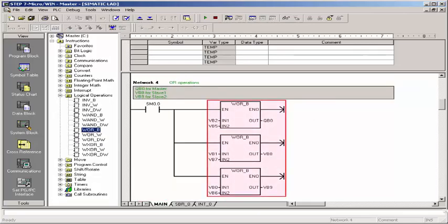The byte-by-byte logic OR connections of rising and falling running lights per PLC occur in network 4. For the master, the result is directly output to QB0, and for the slaves it is intermediately stored in V memory byte 8 or byte 9.